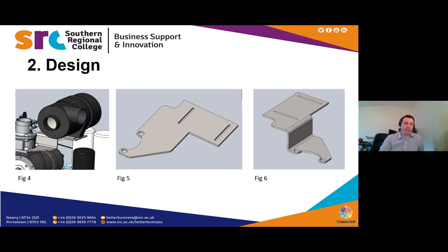Additionally, you can over-design the simplest thing, but you can design a simple thing well too. This bracket I was able to design using the sheet metal function in SolidWorks, where I was able to make one part. If you look at number 5 there, that's a flat pattern, and number 6 uses 2 folds. That made a part that holds the air filter above the compressor, which means it's easier to mount to the compressor.